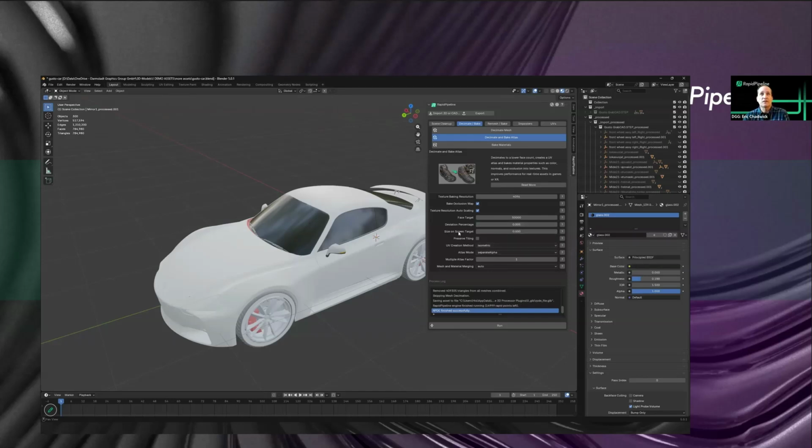You can also do a size on screen target. So for example, I know IKEA has a standard where they set things to a resolution dependent upon how big it's going to be when it renders on the customer's screen. For example, if you have a representation of a car that's a real-time model and you're displaying it on a car LCD inside the car, then the resolution of that screen is going to be fairly small, and you can tessellate or decimate based on that resolution. But it's also a way to do LODs really nicely.